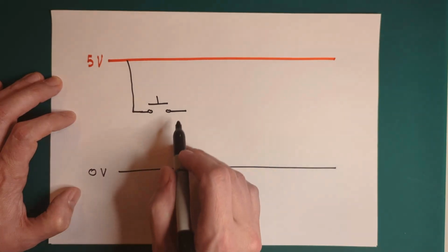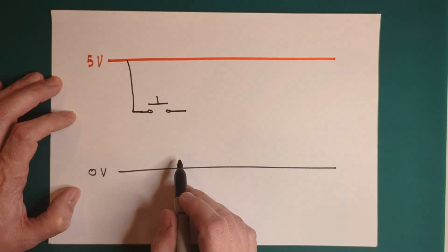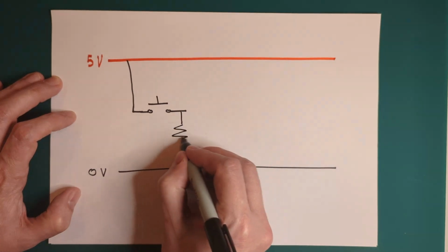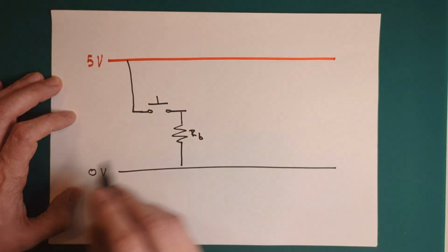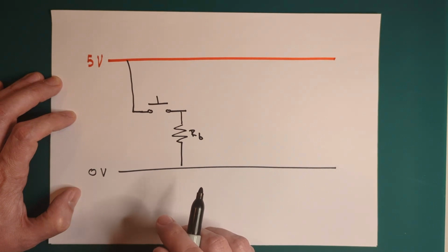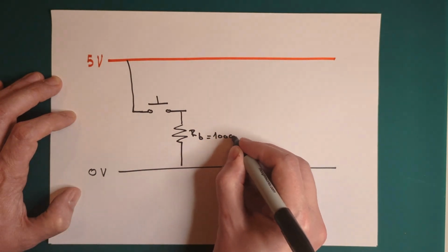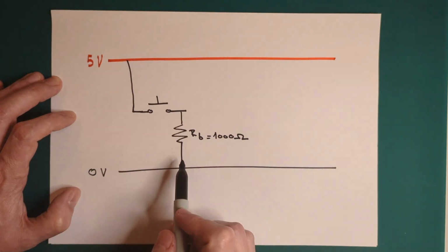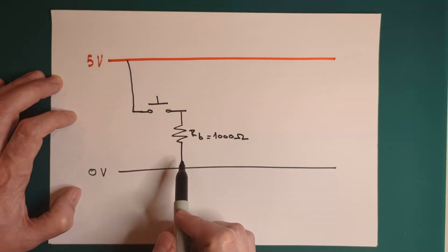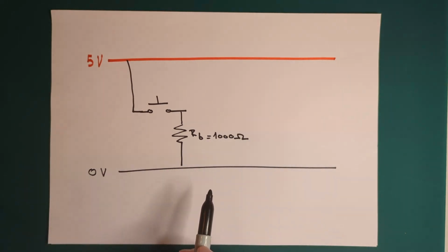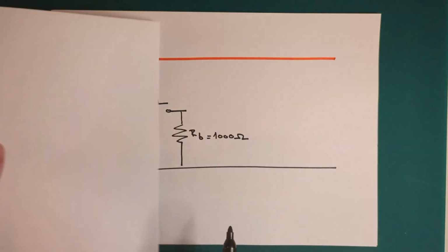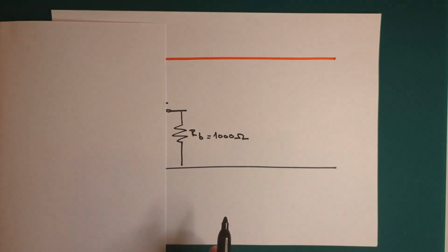And I cannot put a wire to 0 volts directly because that will short my power supply when I push the button. So I added this button resistor, and the amount didn't matter much at this point, so I chose an arbitrary 1000 ohm. The more the better here, because this is just to prevent a short, and small resistances waste more power. I can actually ignore this left side because my problem happens when the button is released. In this case, all of this is disconnected.